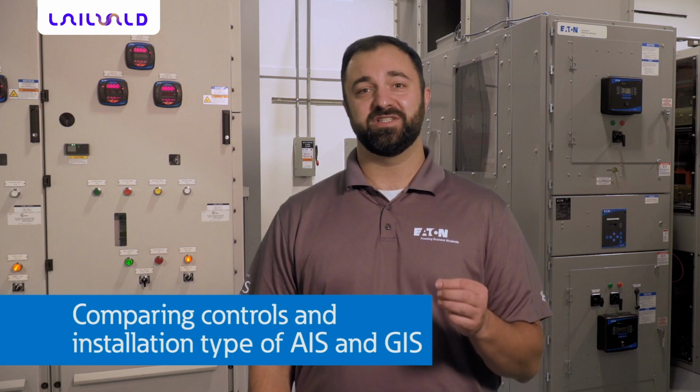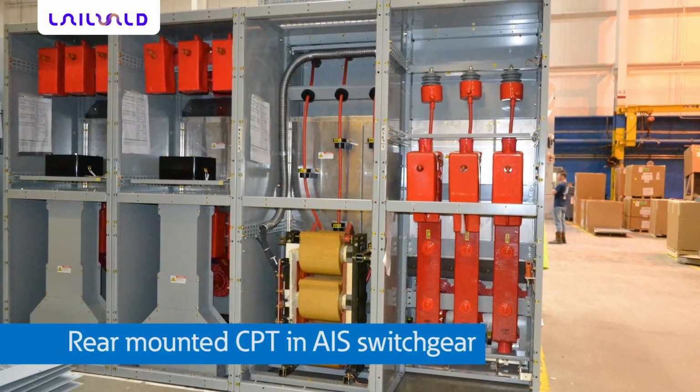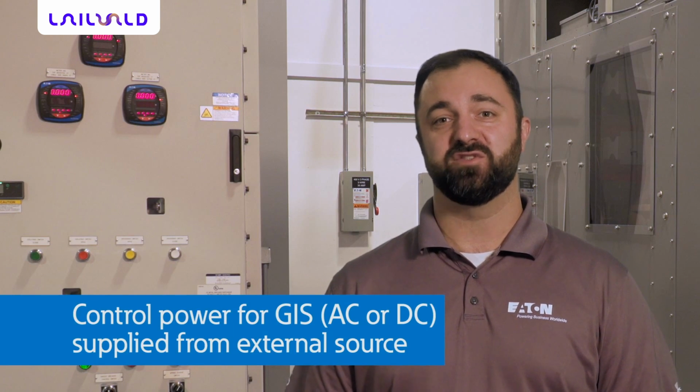If your preference is to use a CPT installed in your switchgear lineup, AIS has the flexibility to provide a CPT mounted within the switchgear. However, GIS does not allow for auxiliary devices, such as CPTs, to be mounted internally. Control power for GIS, whether AC or DC, must be brought to the switchgear from a customer-supplied source.